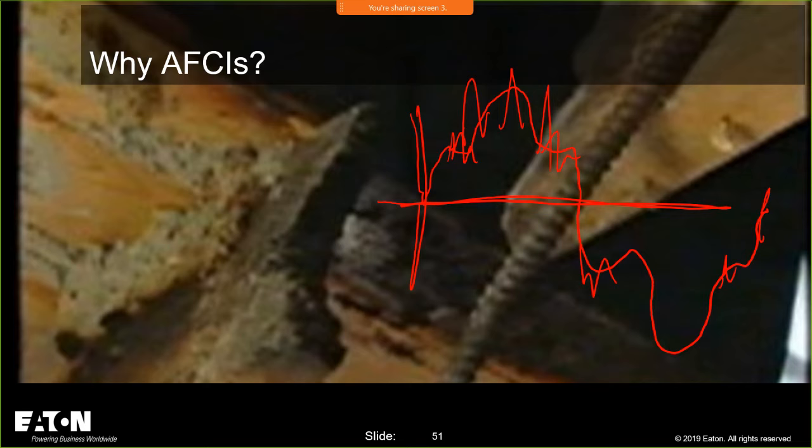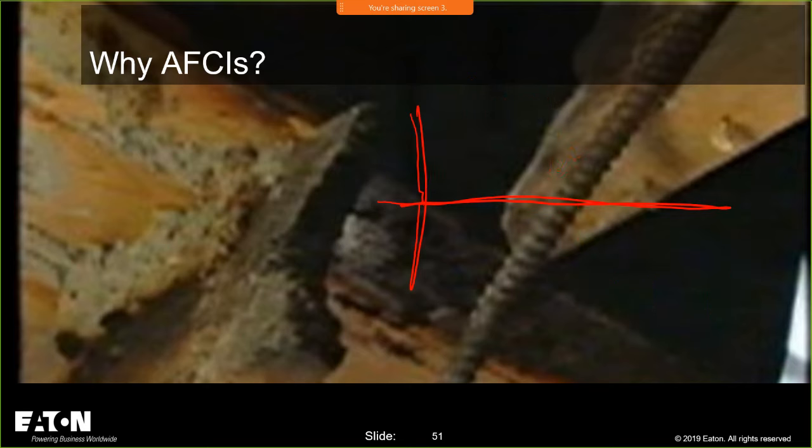I mean, that is just fantastic if you think about it from a technology perspective. I can look and sample a waveform. I'm not looking at RMS anymore. I'm looking at 60 hertz. I'm looking at higher frequencies, and depending upon the algorithms, which are all proprietary information, I might be looking at various frequencies and looking for abnormal signatures at one frequency, an abnormal signature at a very high frequency.